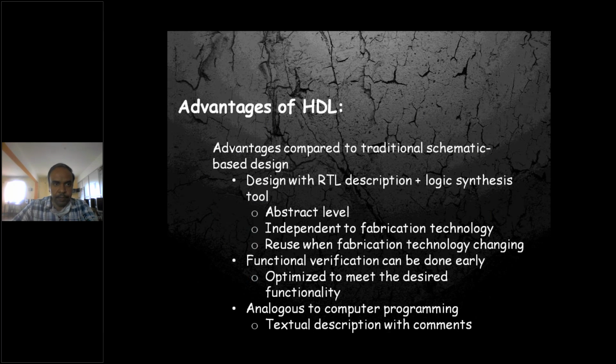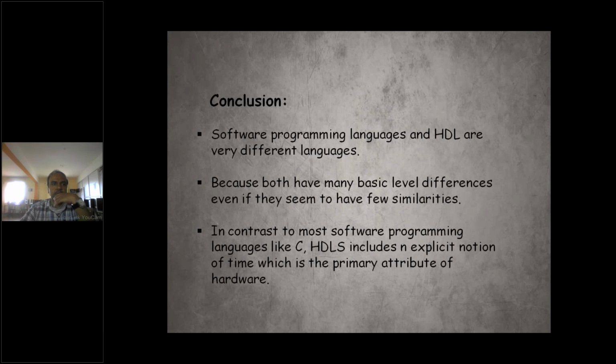Advantages of HDL compared to traditional schematic based design. Design with RTL description, logic synthesis tool, abstract level. Second one is independence from fabrication technology, so you can reuse the design when fabrication technology is changing. Functional verification can be done early, so the design is optimized to meet the desired functionality. It is analogous to computer programming, a textual description with comments.